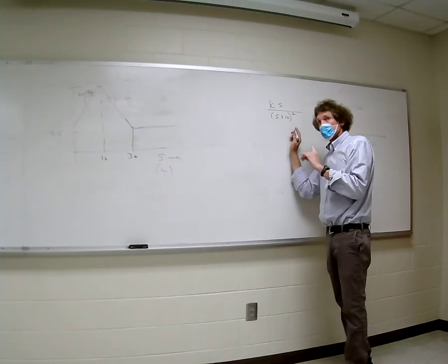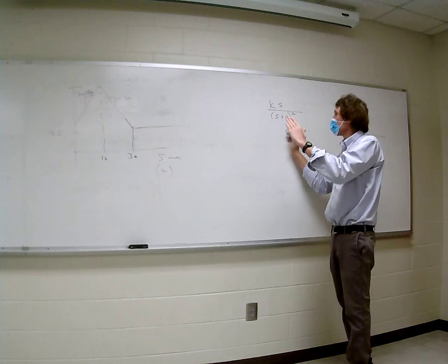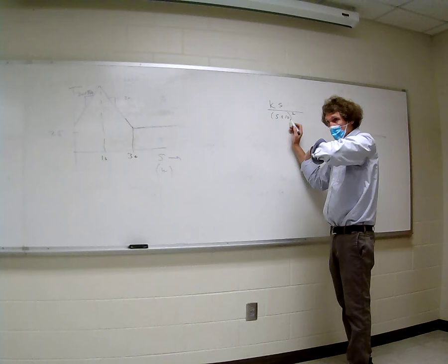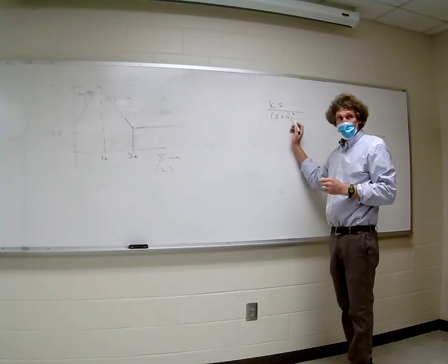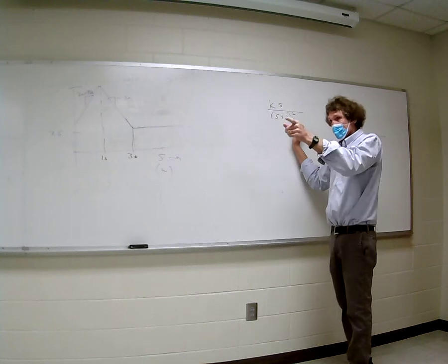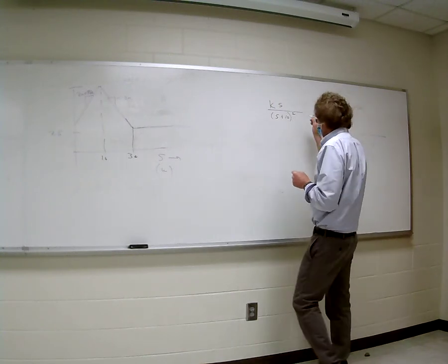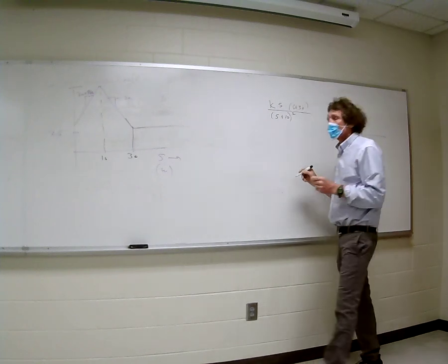If it was just S plus 10, it would level it out. We're going up at 20 dB, this would take us down to 0 dB increase, and if I put a square there, now it's going down at 20 dB. You all follow me on what I'm saying? What else? There's an S plus 30 in the numerator. All right. Now, that's the general form, right?